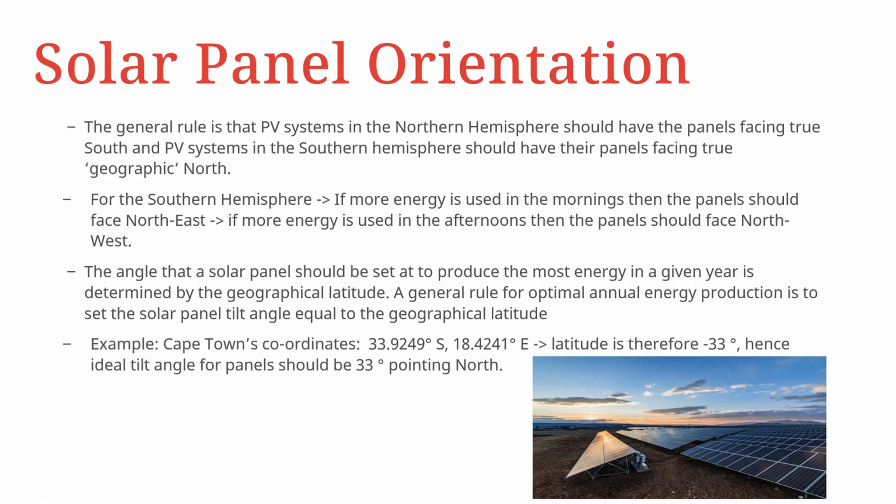And I've taken my location, for example, in Lagos, Nigeria, with a latitude of approximately 6 degrees. Of course, we're in the Northern Hemisphere. That should now be the tilt angle that would provide the optimal energy production. But in this case, it should be facing due south. Good. But of course, there are places like Nairobi, Kenya, that have locations on the equator, that is at 0 degrees latitude. So panels in these regions can, of course, be placed horizontally.